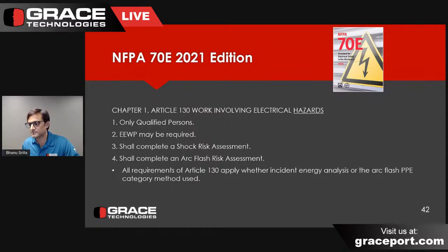All right, so basically the permit, again, it may not be required. Like 90% of the time it's not. And it's really repair and alteration that we want to eliminate. And if you do have justification, then you can use the energized electrical work permit, right? But you have to have solid justification. You have to be able to defend it, right? So again, misunderstanding about the permit, that we need it all the time. Well, technically you do, unless it's exempted, but there are exemptions. And then you can add additional exemptions in your company's electrical safety program, right? These are voluntary standards. Interpret them, figure out how to apply them in a reasonable manner that's practicable in the workplace. So take additional exemptions and add them to your company's electrical safety program.